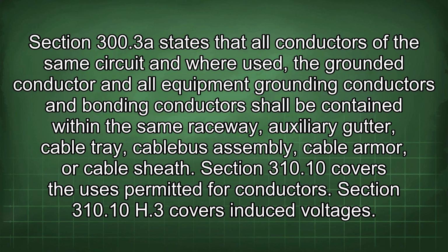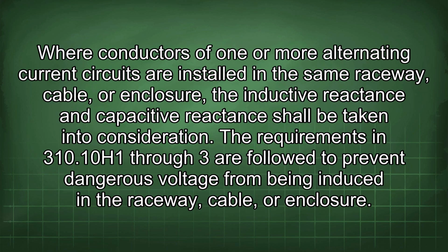Section 310.10(H)(3) covers induced voltages. Where conductors of one or more alternating current circuits are installed in the same raceway, cable, or enclosure, the inductive reactance and capacitive reactance shall be taken into consideration. The requirements in 310.10(H)(3) are followed to prevent dangerous voltage from being induced in the raceway, cable, or enclosure.